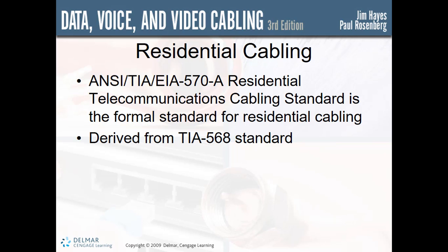The 100-meter link length is carried over from the TIA-EIA 568. Two grades of cabling, jacks, and distribution devices are specified, grades 1 and 2. Grade 1 may be Cat 3, which will likely not be used, and grade 2 must be Cat 5. Cat 5E is recommended. Grade 2 distribution devices are required to be larger than grade 1, and grade 1 outlets terminate one 4-pair UTP cable and one 75-ohm coax cable.